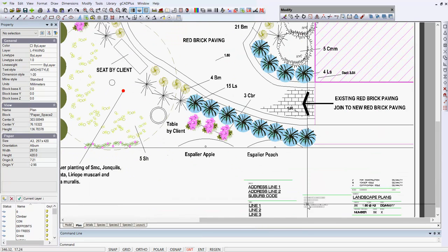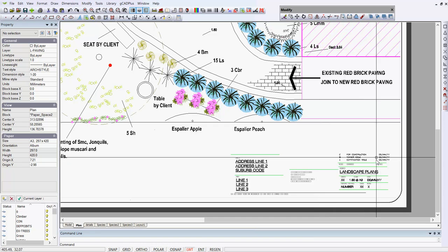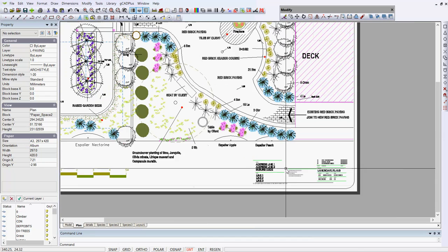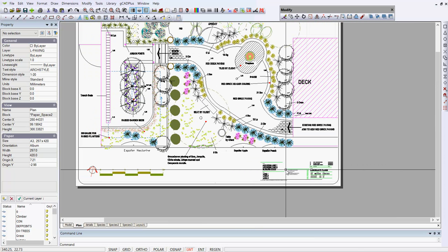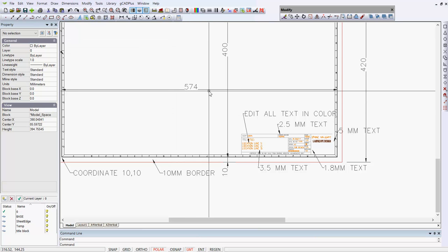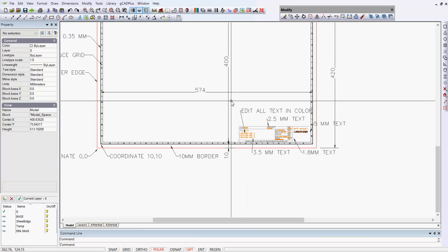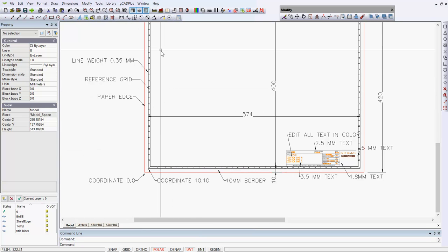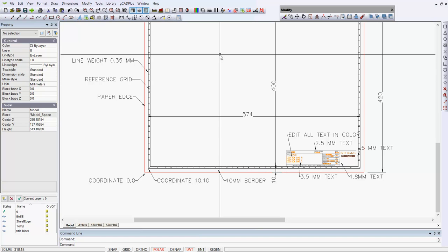Here we've had to put slightly more information in, construction and tender issue information, but the title block is still a relatively minor part of the presentation. However, you may find that your local authority requires you to present a drawing on a drawing sheet with some sort of reference grid, which will have letters and numbers so that you can discuss a certain part of the plan by using a reference code system.